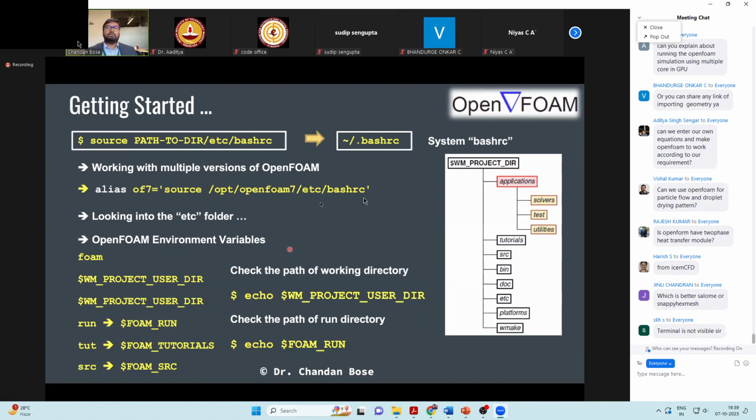But if you really go to the accuracy level of comparing with some experiment, you need really a good mesh. And a good mesh is the first tick off to get the best solution out of the CFD, right? Otherwise, you can get anything out of CFD, and instead of being computational fluid dynamics, it will become colorful fluid dynamics, which will not be validated with your experiment.